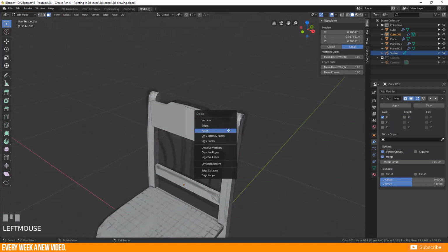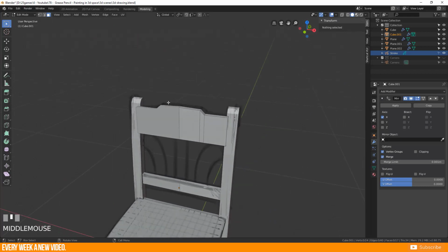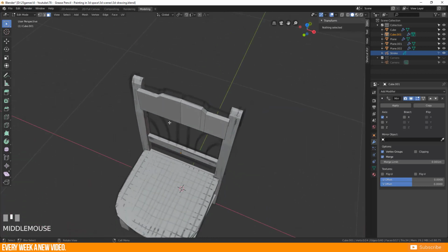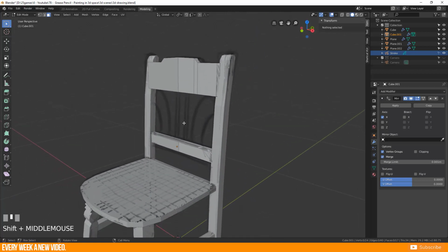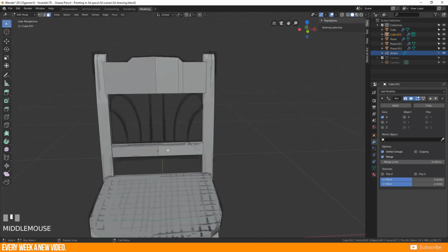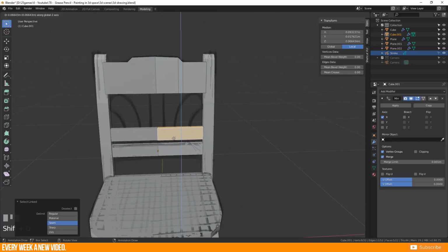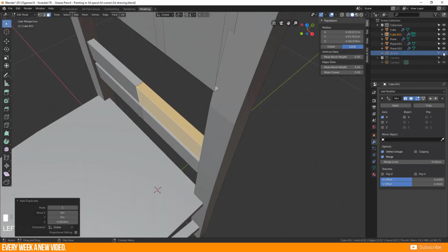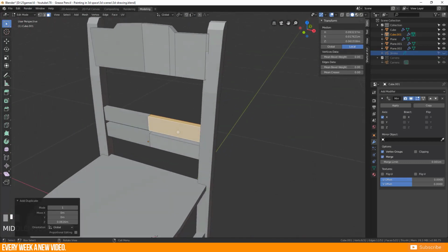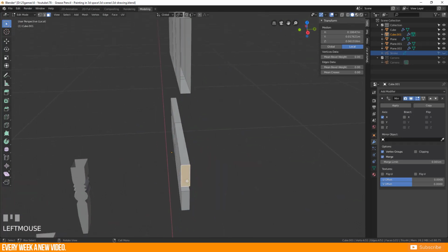We don't need this face at all, so delete it. It can be sticked to this mesh as well. Well, the next thing is I will duplicate this again, bring this a little bit upwards, and this is annoying me, and isolate the view so that I can hit this face here.